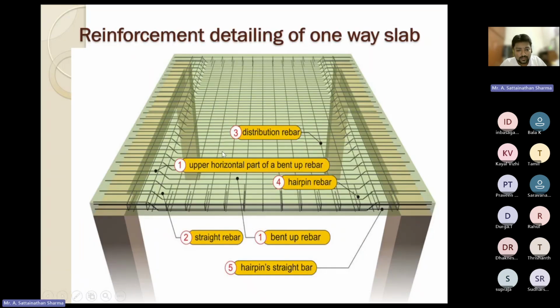So this distance, you are providing the bars, right? This bar, this one. So 1 bar, 2, 3, 4, 5, 6, 7, 8 as it goes on. Correct? So this distance is 260 mm. The bar is 10 mm diameter.